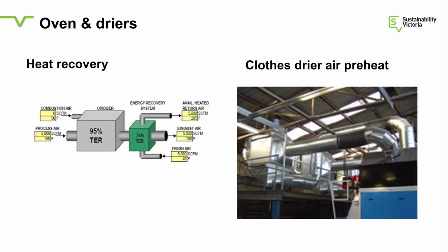Look, another example is clothes dryers. Big industrial clothes dryers use a lot of energy. And whilst most of them in this country have humidity control, if you look at your little domestic one at home, most of those have humidity sensors in them to minimise the amount of exhaust, believe it or not, a little electronic control system. But in the big industrial ones, they do that as well. So they measure the humidity, and if you're not over drying, you recirculate. So you're not pumping too much air out of the dryer, you're optimising it based on the dryness of the clothes during the batch.